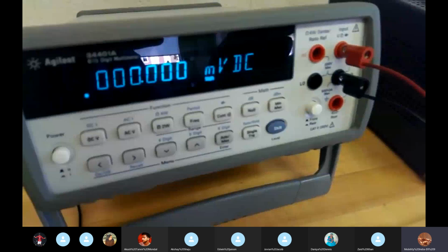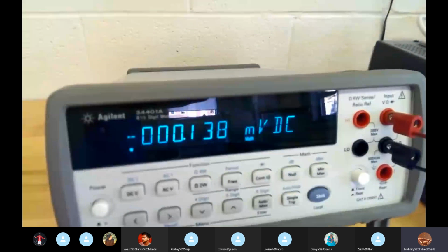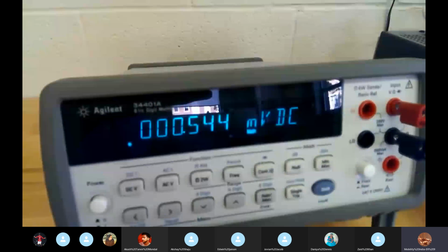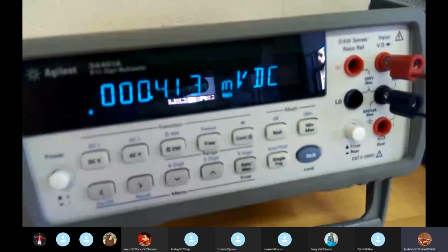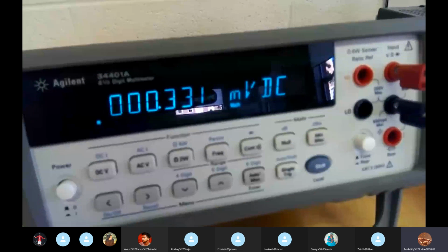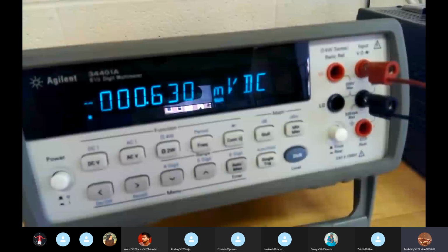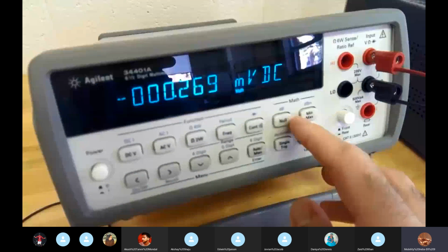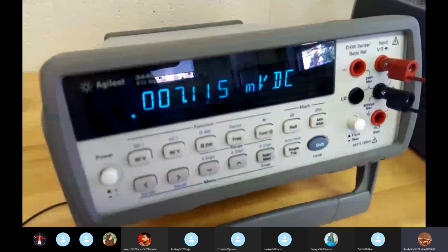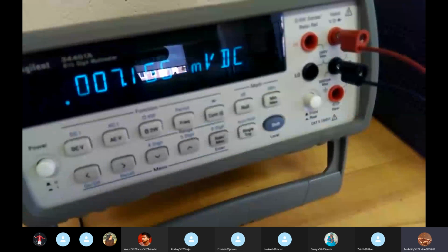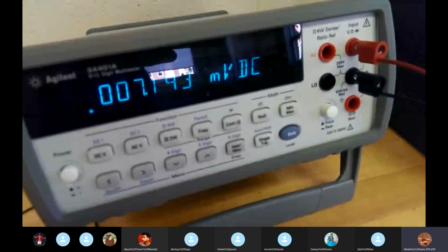See the resistance increase again. Take that number, remove the weight, unnull, and keep repeating that until you have hung up the full 5 kilograms worth of weight plus the hook on the cantilever. So that concludes the instructional video for experiment number 5, strain gauges.